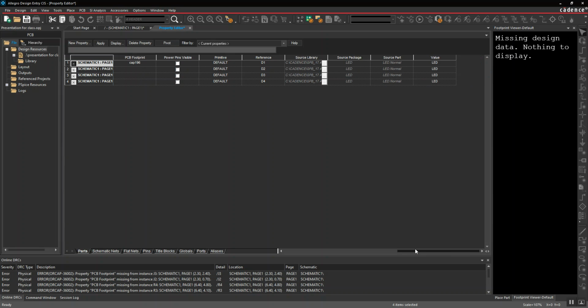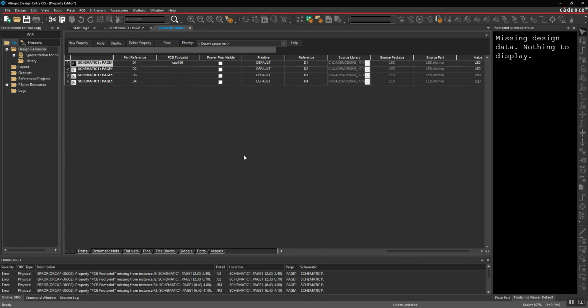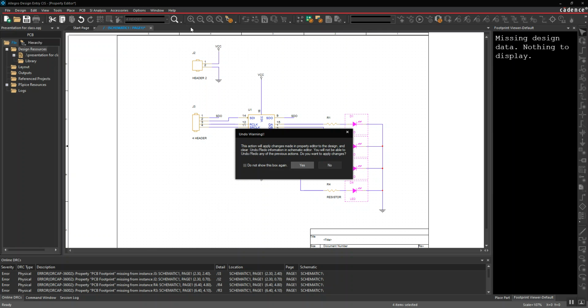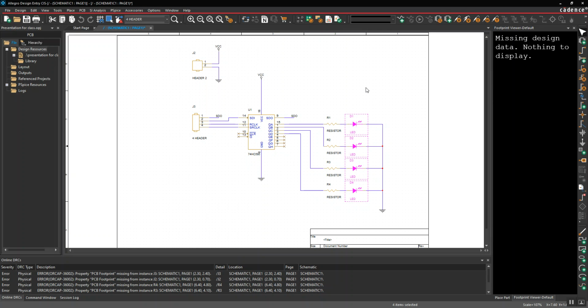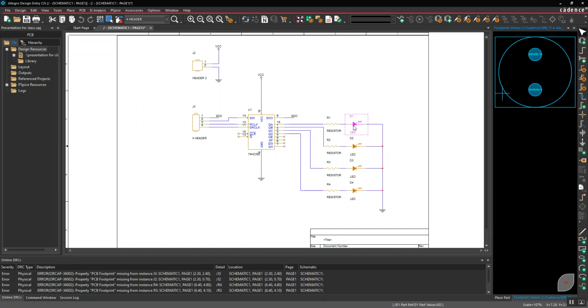So you can highlight all the parts like that, or you can select individually, which we'll do here in a second. So you can do this and drag down, and now all those are cap 196. So we're going to do it another way here in just a second. Edit that, and now you can see that all these have the footprint. And that's also the same footprint you'll use for those simple capacitors, like bypass capacitors,